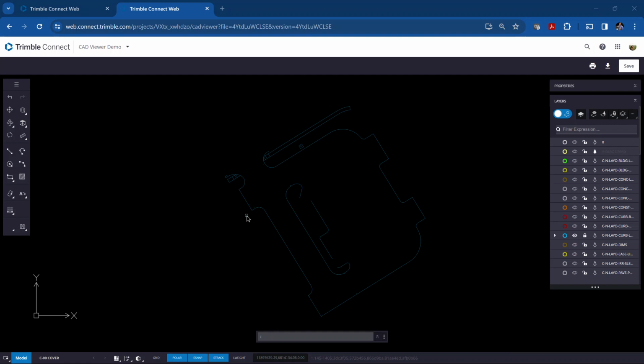So our next object or feature we're going to work with is the hatch pattern. A hatch pattern will fill in an area with either a shading or a particular pattern of lines. So you'll see hatch patterns being maybe a crossing segment or basically a series of triangles and dots representing concrete or some other kind of heavy duty asphalt area maybe.